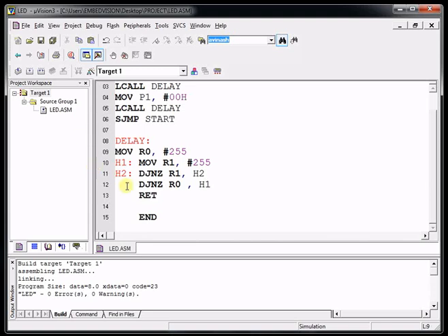Correct. Now you can generate hex files. For generating hex files, save file and compile that file, build target. Correct. Now you can see that creating hex file, it has created the hex file with name LED. So LED name is basically the name of the file as well, and it is the name of project as well. So hex file is always generated with the name of the project, not with the name of the file. So that is the complete process or steps how to use Keil.